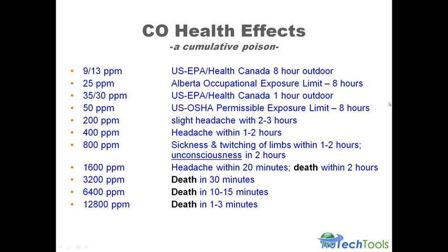So we need to be concerned with CO air free, because it's going to give us an apples to apples comparison of saying, when we take the dilution out of the equation, how much CO is actually in the flue gas. And that's what CO air free is, the standard. If you were taught the other way, it's wrong, because it's giving you a raw CO reading, which is absolutely valueless for understanding how much CO is in the air. CO air free also applies to ovens.